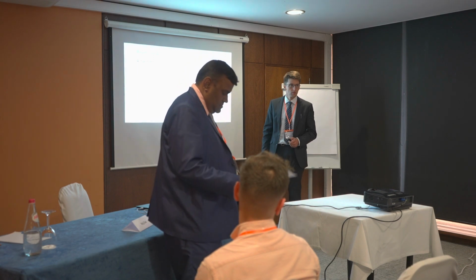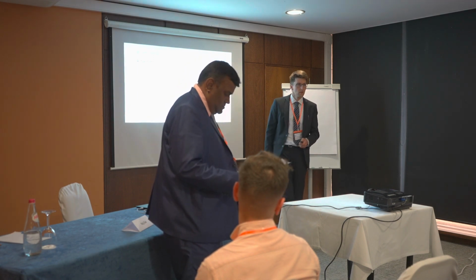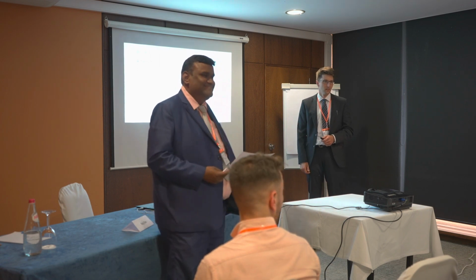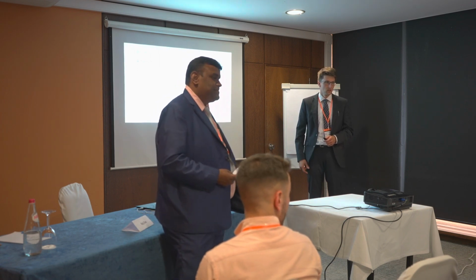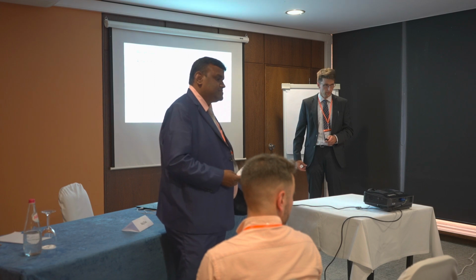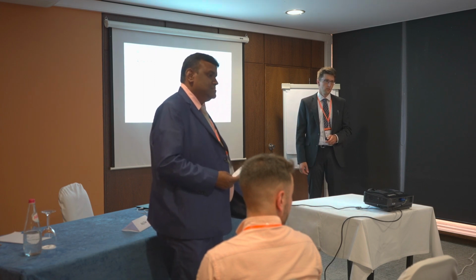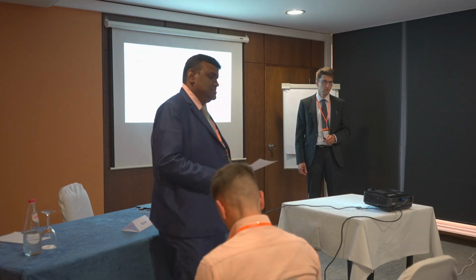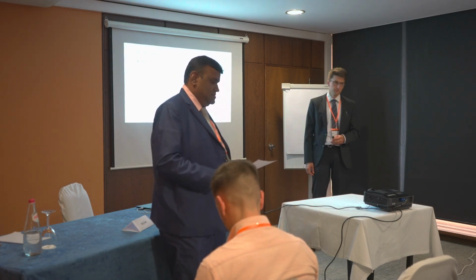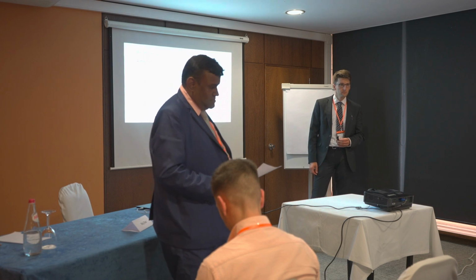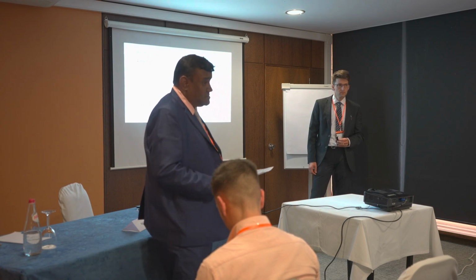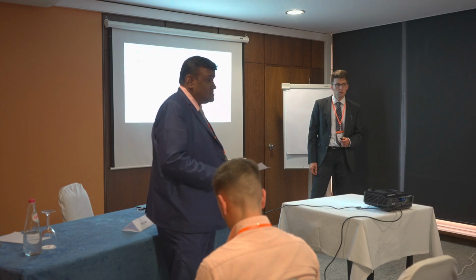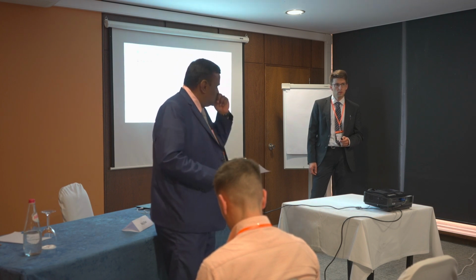And actually, the other question, if the chair allows me another question. Yeah, sure. You say you can also calibrate with the experiment, right? But what is not clear to me is the reflected pulse. It depends on the stress measured from the specimen, right? So you are calibrating, assuming you know the properties of the material, because in condition of dynamic equilibrium, the reflected wave depends on the property of the material.